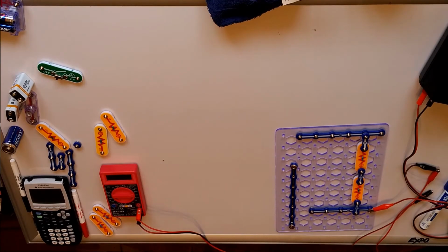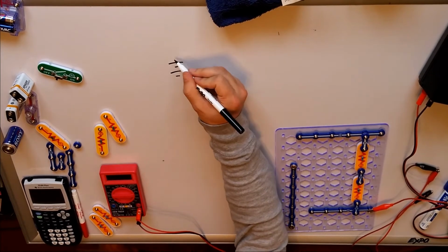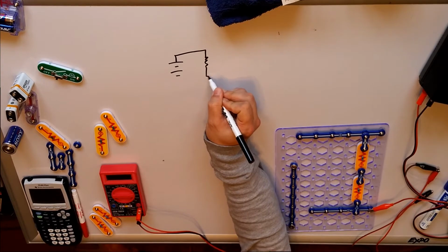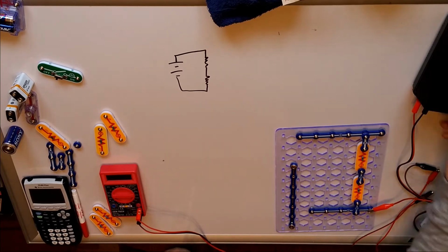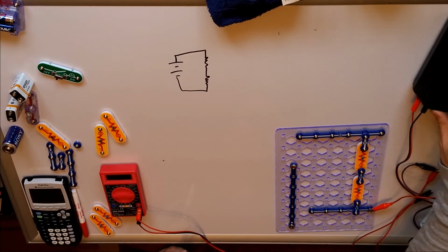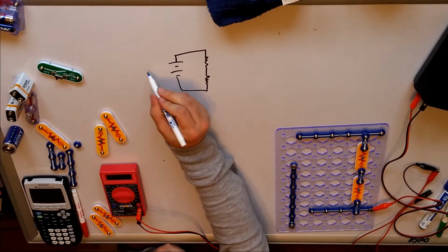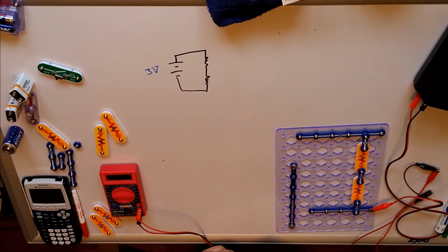Okay, sorry about the jump cut there. I was running into some issues with some of the equipment that I had set up. So we're going to go through and we're going to see how we can come up with this equivalent resistance. So I've got the following circuit. I'm going to have a voltage supply, basically a battery, that's going to come over here, and I've got two resistors that I've put in here. So here's my power supply. I was trying to work with some batteries, but I think they kept fluctuating some, so I've gone back to a regulated DC power supply, which is going to give me a good solid output. And I've got it set right now to 3 volts. So 3 volts. And it should be pretty close to that because it's a nice regulated DC power supply.